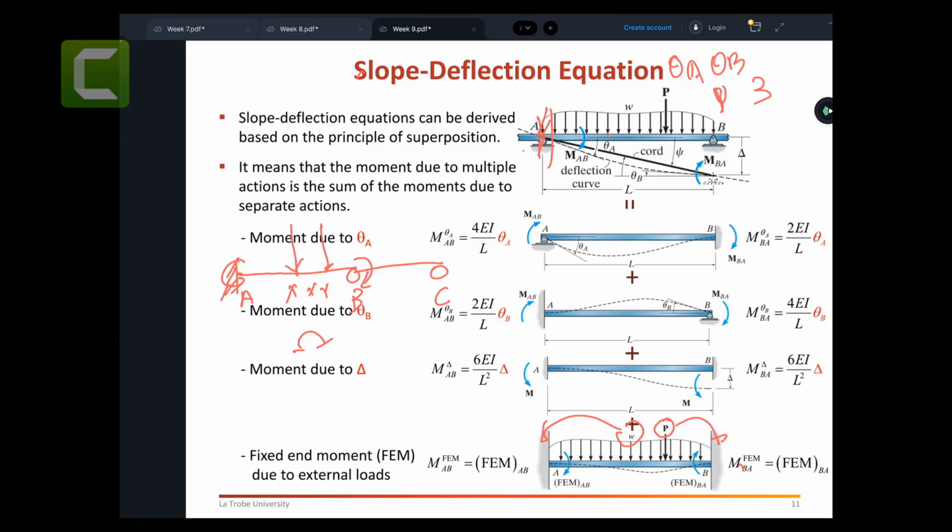Then the next job is to go and find the fixed end moments in the whole beam, where you want to transfer all your internal forces to the joints. Everywhere you put the clamps, at that same clamp you want to throw all the forces to that clamp.